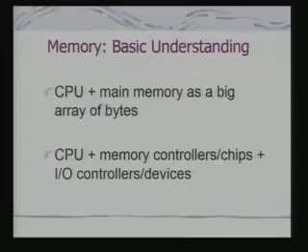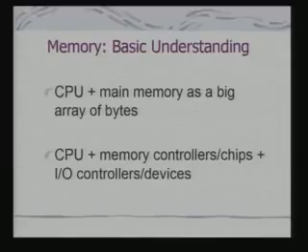Let's recapitulate our concept about the memory and its usage in an embedded system as well as in a general computer. So we can view the CPU and the main memory as a big array of bytes, and that basically is my microcontroller or a computer. We can also put in an in-between memory controller to interface with external I/O devices as well as memory. In fact, we have seen a number of these processors or processing cores targeted for embedded systems have memory interface units provided for this purpose.